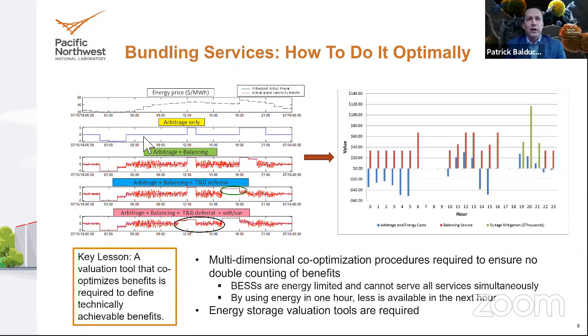So we have a tool called the Battery Storage Evaluation Tool. And effectively, we're defining a duty schedule for the next 24 hours, and then that is updated on an hourly basis. You can see here in the first panel on the left-hand side, energy prices. And if you're providing arbitrage only for this 5 megawatt system, you can see it charging up in the early hours and discharging around lunch and in the early evening hours.